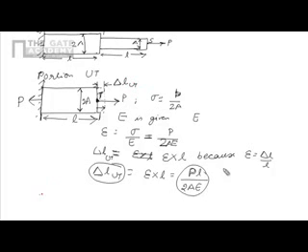Okay. Now let's take the other portion. The other portion is portion ST. Now ST, if we isolate ST, diagram can be drawn like this. The applied force is P. Obviously the reaction also has to be equal to P. Its length is equal to L and its area of cross section is A. Over here the stress will be equal to P upon A. This is stress.